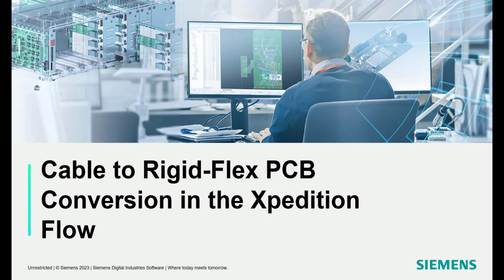Today, we'll be covering the process of converting an existing cable design in Xpedition System Designer to a rigid flex PCB. The cable logic will simply be copied to a new board design in System Designer and relayed to a new flex PCB in EDM. The physical board geometry will be modeled in the mechanical domain, Siemens NX, and sent to the electronics domain for